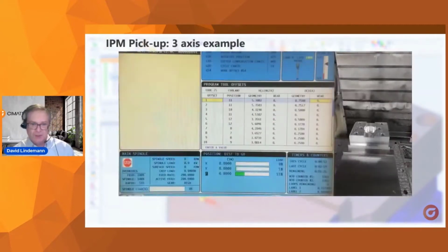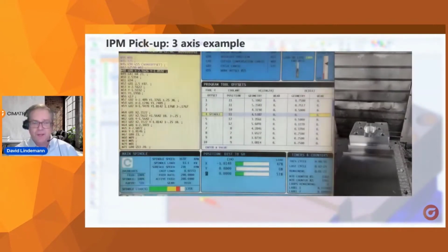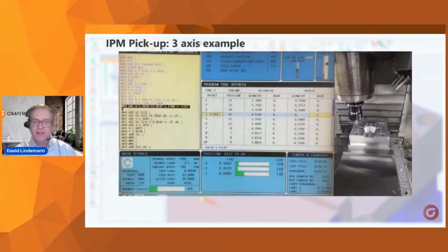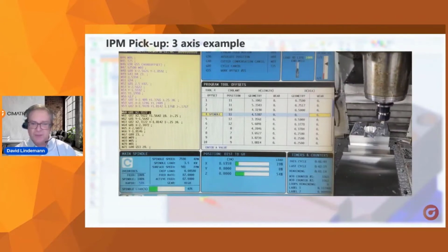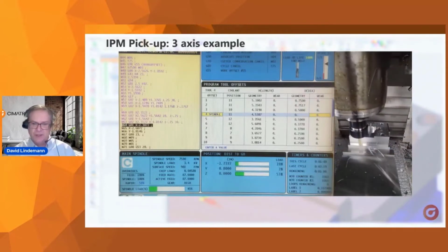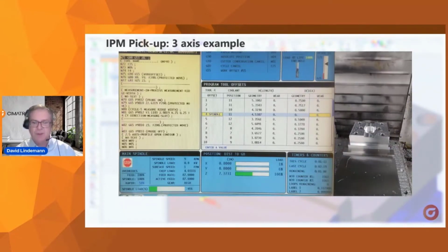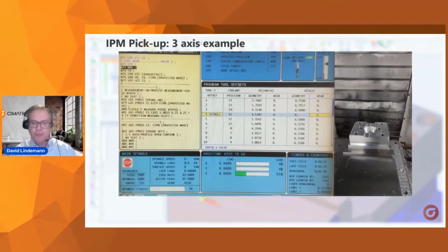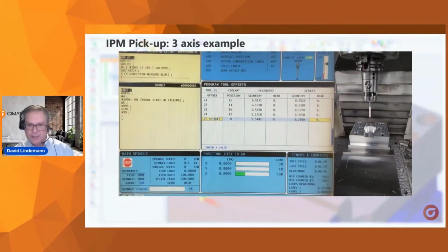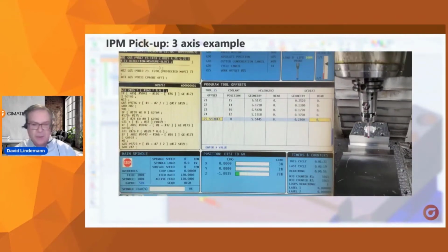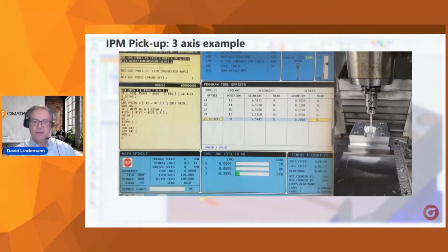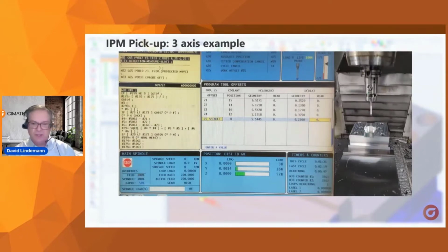We'll continue this program here. It starts from G55, just like we asked. And now it's going to go around taking that cut. You'll notice the offsets and the positions flash, we highlighted on the controller for you so that you can see right when it's doing the work that it's doing. Now, as we come back with the probe, the information we get is going to appear on your lower right of your controller screen. It's going to populate in label 1. And that will be what we use then as we make the adjustment to the cut.